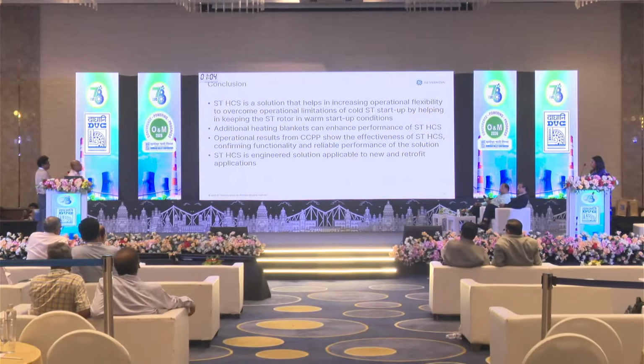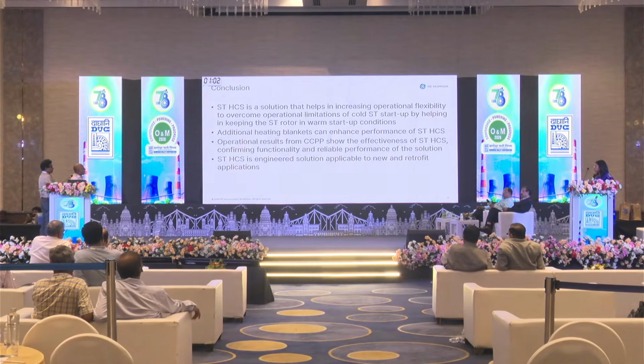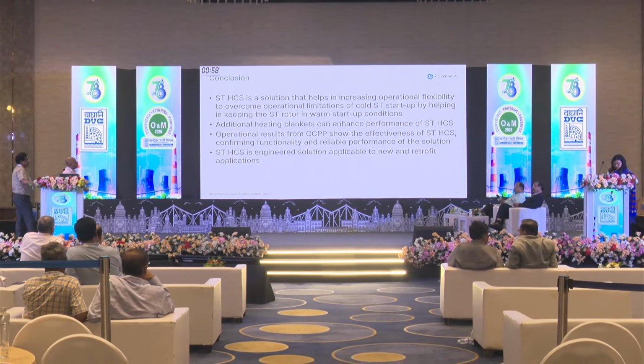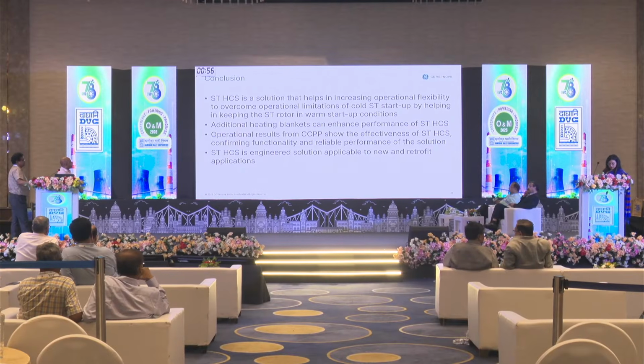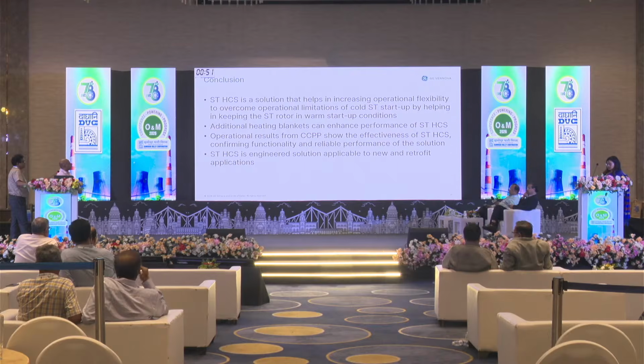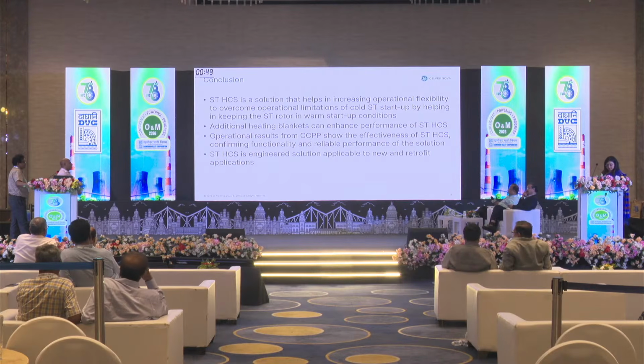Basically, this technique is only for cold startup. Yes, sir, because with hot air, we have checked it. With hot air, we are not able to manage a temperature like 450, which is actually the start permissive for the hot start. But around 320, 330 is the right calculation and right design, and if we can make it around 320, 330, then we are getting the warm-up permissive, not the hot start, sir.